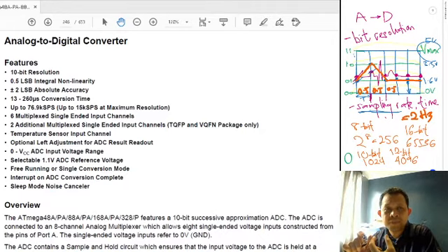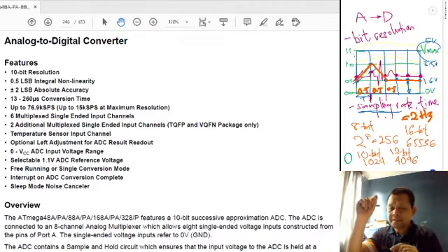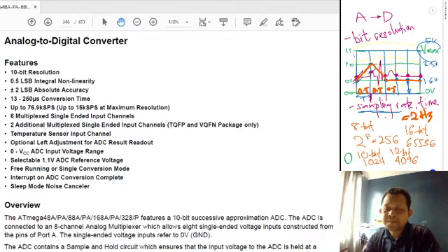So just now you're using an 8 bit resolution ADC, you only need 1 byte. But when your resolution is 16 bit, you need 2 bytes, so you need more memory. If your resolution is 24 bits, you need 4 bytes to store one value which represents the voltage of your signal.